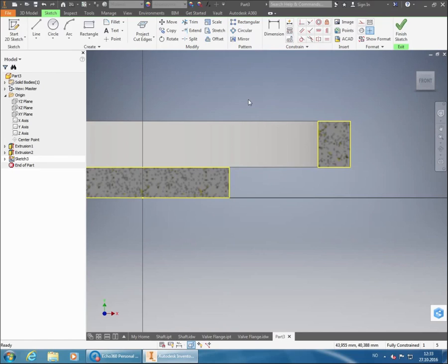But down here the curve is going this way, so it's bending away from our extrusion, and so we're going to have an opening between the disc and the extrusion, which means that we are going to have to pull our extrusion somewhat into our disc here in order to avoid this. I can show it a bit better if I flip my view a little bit there.